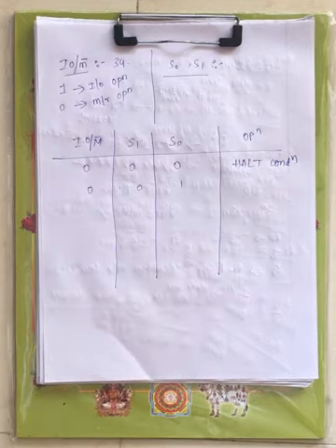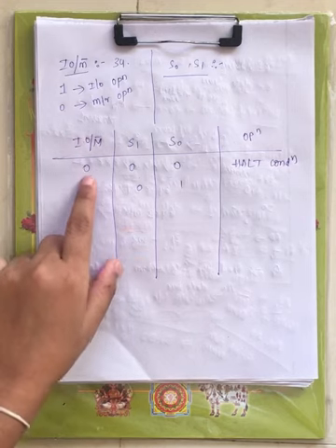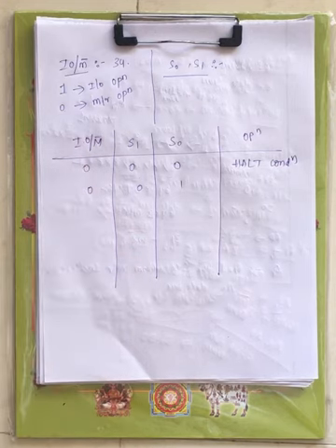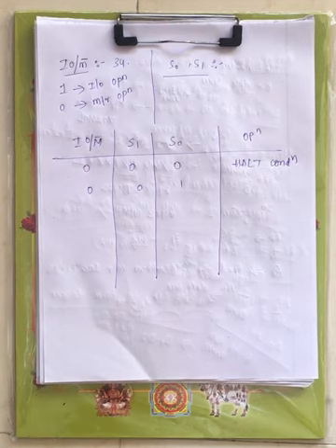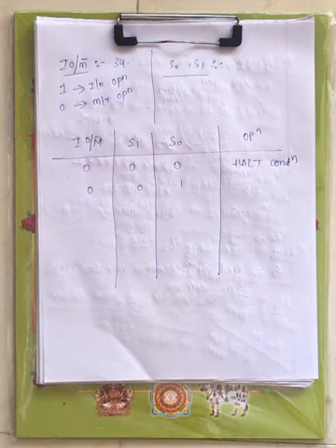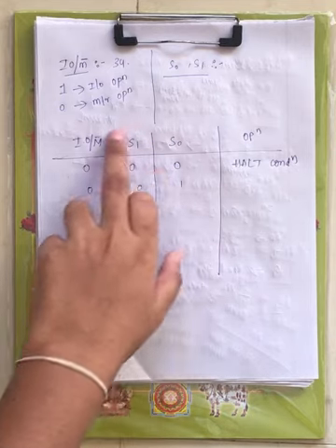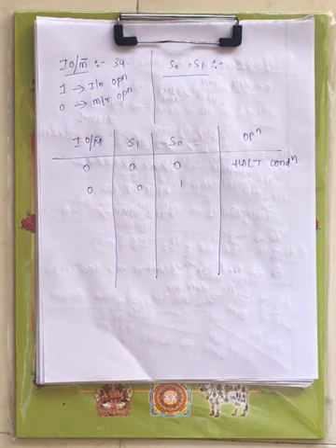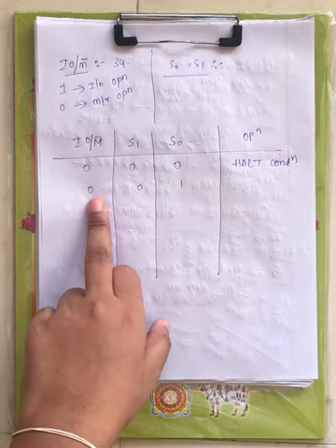Now when it is 0 0 1, which operation is it? Memory operation. Through the memory, either you can read the data or you can write the data. Memory stores the program, that is, the set of instructions in the low level language. From that memory I can read the data or I can write into that memory, and whether to read or write is decided by the status signals.